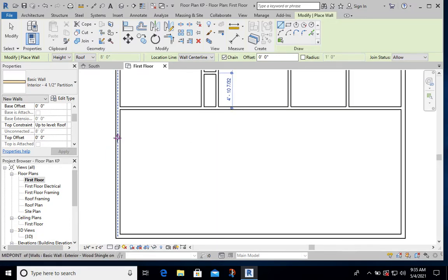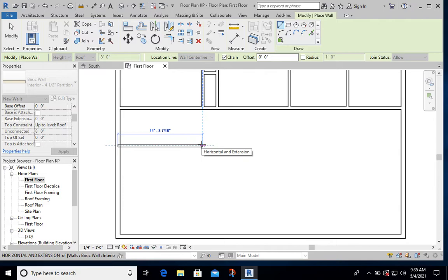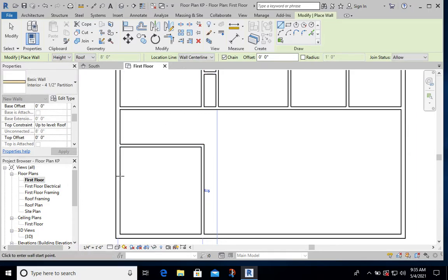We have a couple walls left. So I'm going to put an interior wall here. And if you hover until you see that dotted line, that's automatically going to line up that wall. So now my width dimension for this room, because this one was 12 feet and this one was 12 feet, that means that these two are now lined up. And I actually don't have to dimension it, but we will still check it. I'm going to put in a little closet here and a wall for my walk-in.